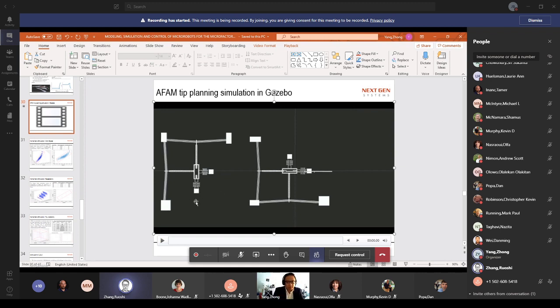So basically, here's some simplification from my model. You can see this microrobot. This micro stage, the XY motion is not decoupled. When you push this part, it will have some motion on this part. Do you know what I mean? Yes. So basically, this micro stage design cannot bring a pure X and Y motion. But in my model, to simplify, I just assume they can have pure X and Y motions.